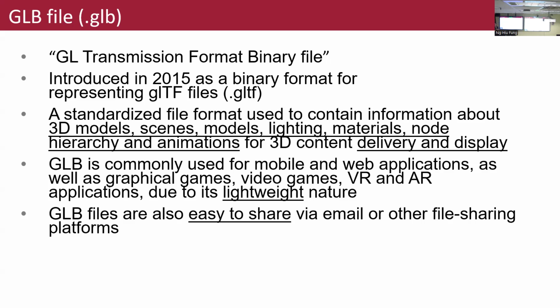So today when you want to create the metaverse, do not use the .ma, .mb, .max, Blender files, etc. Try to use some open source format, because when you use an open source format, you can ensure that your files and your models can be used on different platforms. So the first one we are going to learn is GLB. GLB is a binary file dedicated to 3D models, scenes, lighting, materials, and all sorts of animation for the 3D object.